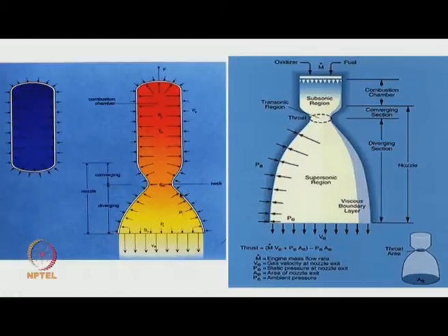So, the net force, if you take a small element here or here or here, anywhere, if you take a small element of metal or wall, the net force exerted on this wall is actually due to the difference in pressure across. So, this minus this pressure times the area is the net force that is acting on the metal wall. This is an extremely subtle concept. Notice that I can redraw this picture by simply subtracting this arrow from this arrow and then removing everything here and then redrawing the picture.